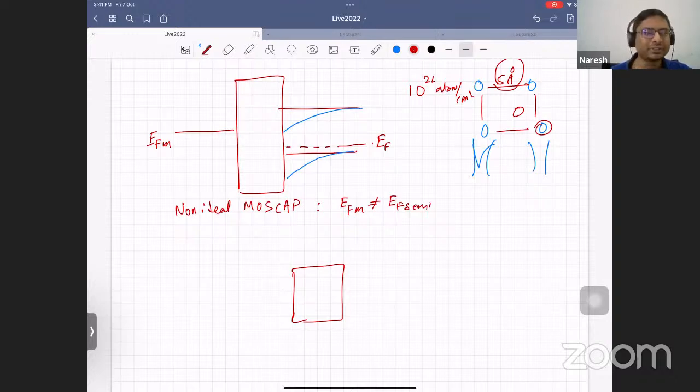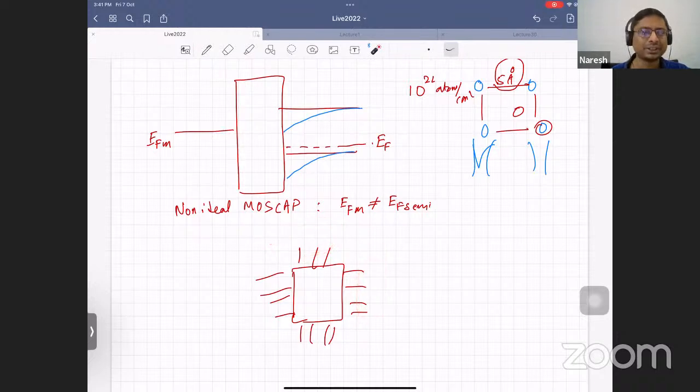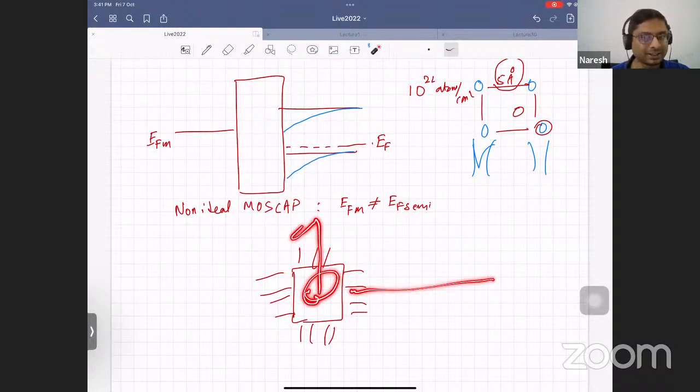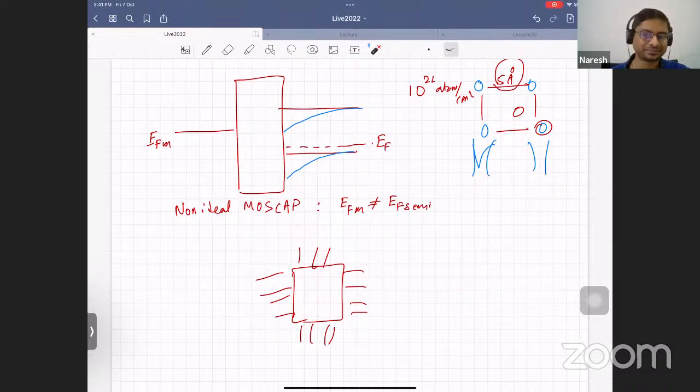You have amazing computation capability here. Think of a graphics card, a very good computation engine. But then it has to interact with the neighboring peripherals, for example the memory, so many buses, so many things. The data has to come from outside. Now it has come to a point where the amount of power required to bring the data from outside into the chip for performing the computations and sending it back has become a significant part of the overall power consumption. It's increasing greatly, and you don't have enough bandwidth to bring the data in. So if you can bring it in by photonic signals, that can be much more efficient.